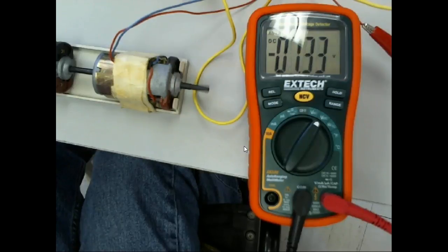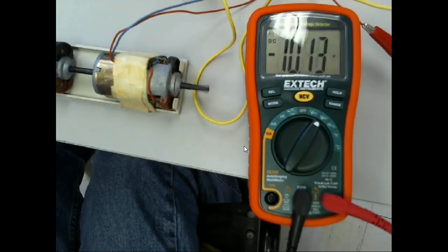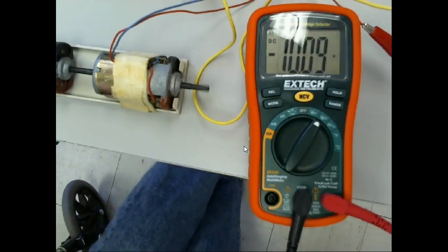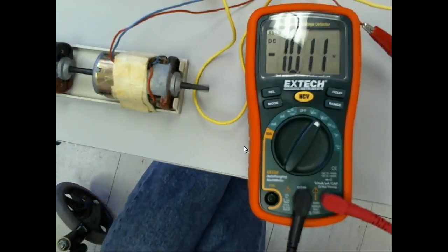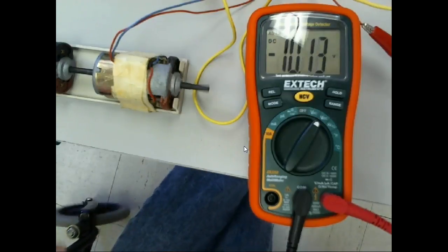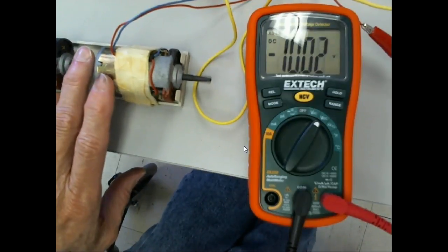But what I'd have to do is run it at its rated speed. I don't know what this motor's rated at. I think 15 volts. And that would be my output, 10 volts, right? And then that would be my transfer function. But before I get a transfer function, I would have to measure the speed of this motor at that voltage.